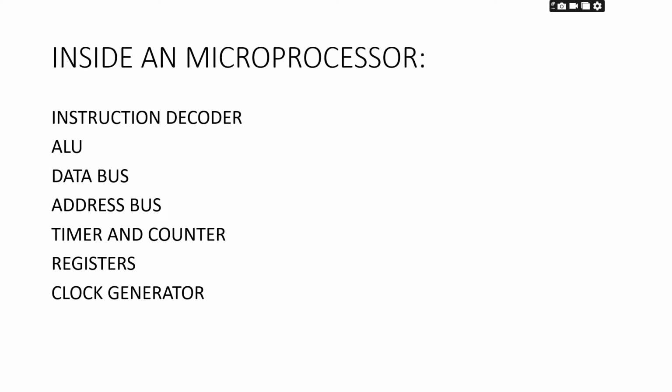What are the data bus and address bus? Why do we call it a bus? In reality, we use a bus for transport. If I want to go from Chennai to my hometown, I usually take a bus. Similarly in hardware, if we want to transfer data from one component to another component, we use the data bus. The data bus is nothing but wires. If we want to transfer an address from one component to another, or send the address of the memory to the accumulator or to the latch, we use the address bus.